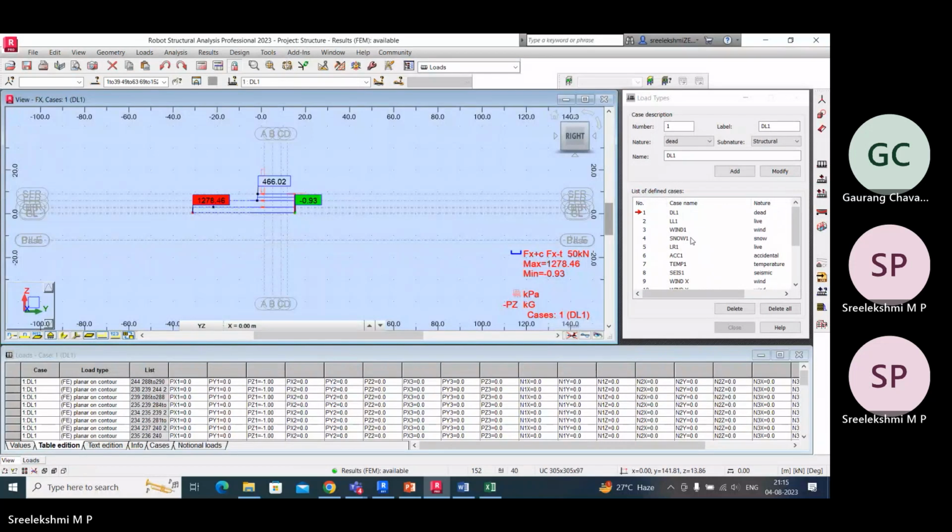If we are doing a model in Robot Structure itself, first of all, we have to create a suitable geometry like STAAD, and after that we apply sections. If it is a concrete structure, we put column sizes or beam sizes, etc. If it is a steel section, then we apply the property. Then the next stage is applying loads. Right from here, we can apply loads.